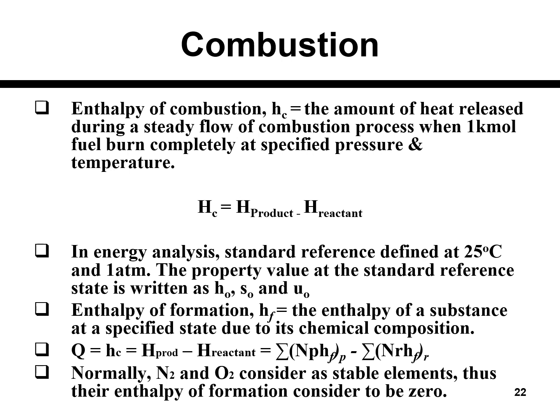So the enthalpy of combustion is the summation of the enthalpy of the products minus the enthalpy of the reactants. Okay, so in energy analysis, the standard reference is defined at 25 degrees Celsius and 1 atmosphere.